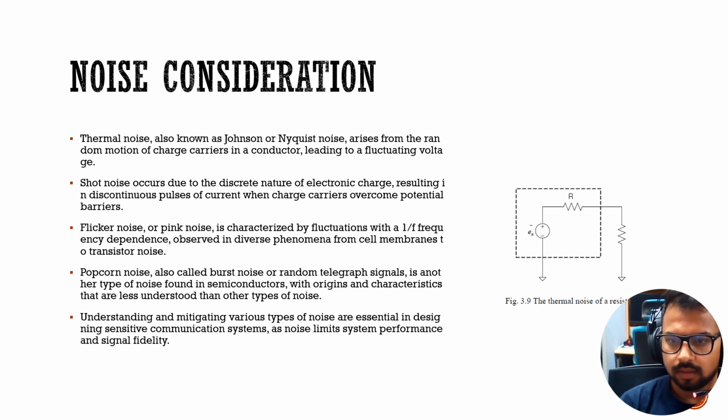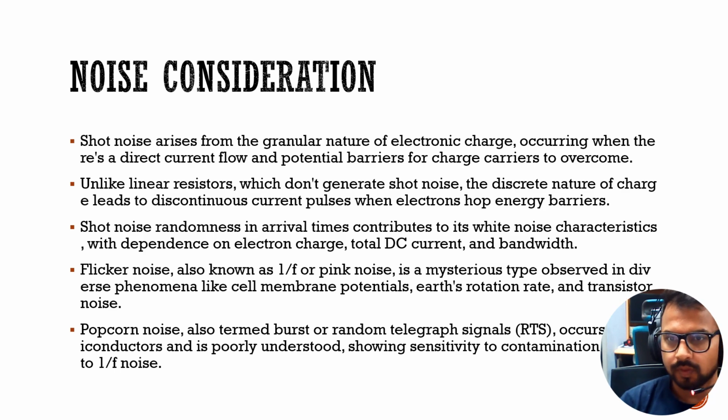Understanding and mitigating various types of noise is essential in designing sensitive communication systems, as noise limits system performance and signal fidelity. You can see the circuit of thermal noise of a resistance and how this noise occurs. We also see the noise considerations. What are the noise considerations? Shot noise arises from the granular nature of electronic charge, occurring when there is a direct current flow and potential barriers for the charge carriers to